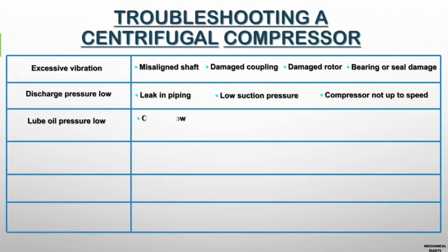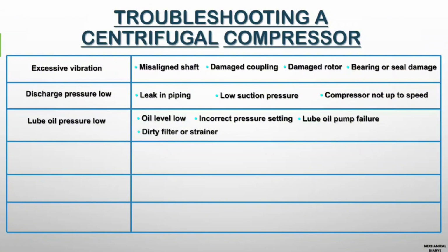Next, we'll move to low lube oil pressure. There are four reasons for low lube oil pressure: low oil level, incorrect pressure settings, lube oil pump failure, or a choked oil filter or strainer. These are the four reasons for low lube oil pressure.